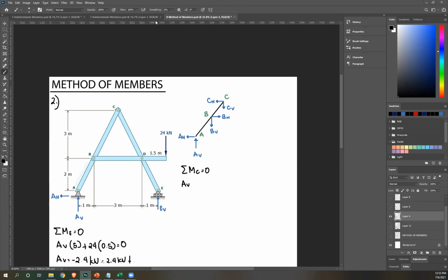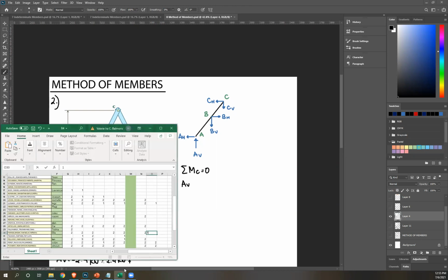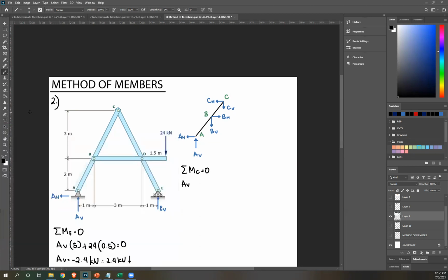Very good, Michelle. It's 2.5. How? This is AB, right? That's the same thing here. And this is C. This is the length that I need. Now, considering this is symmetrical, if I draw a straight line here, that just divides your 3 meters into 2 equal parts. So this is 1.5, right? So 1 plus 1.5, that's 2.5. Okay?